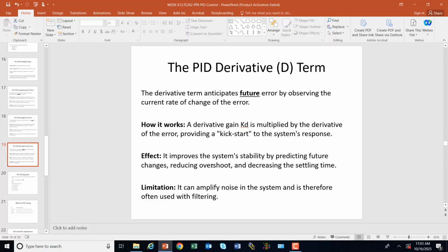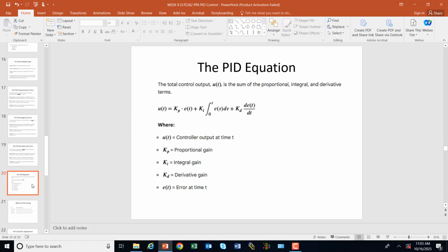Now the thing is, if you change some of these, you'll find that it could really slow the process down. It might take forever then to reach the set point. Okay, and so that's something that you want to watch: it could reduce overshoot, but it might be an hour before you reach your set point. No overshoot, but who wants to take an hour to get there? So between the two, that's kind of what it explained is, P says get me there now. That's the main one that you can kind of work with as your proportional gain.